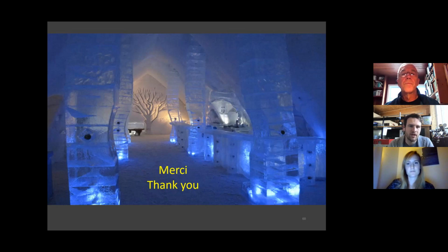So you have a question from Terry Brooks, and they're saying, I can see some cases where we have probably been guilty of oversized embankments with the thought of protecting the permafrost. And they're wondering if you can recommend a permafrost construction manual that deals with the issue of embankment creep due to excessive embankment thickness. I'm not aware of a manual that gives the recipe to design an embankment for creep. The best reference would be Andersland and Ladanyi. They actually discuss a lot creeping of frozen ground, and they have equations to actually model creeping. The chart that I've shown where there is multiple lines was done by fitting the model that was proposed in that book, and then you get a full picture. And the rest of it is a question of tolerance.